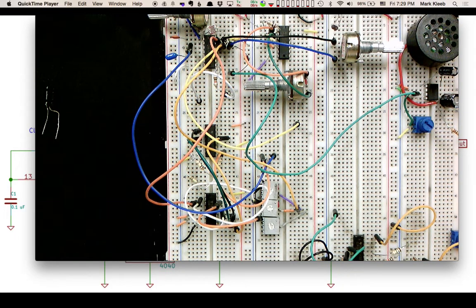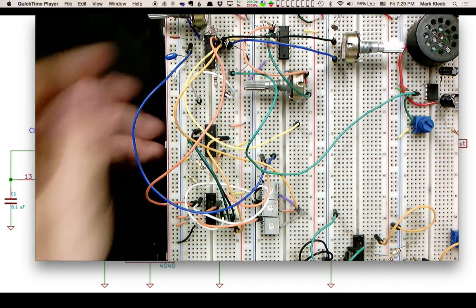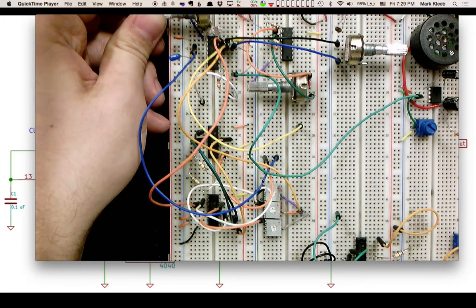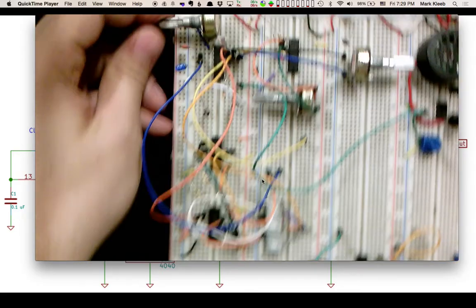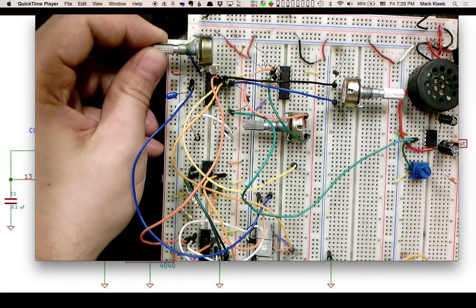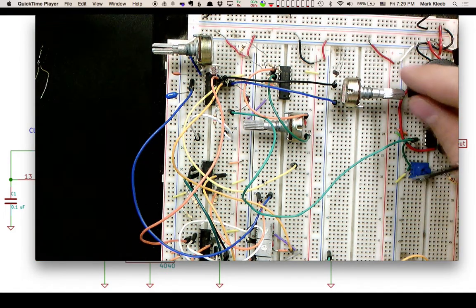And then everywhere that I hear that low frequency, it's because I don't have a trim pot hooked up to that pin. So it defaults back to my base frequency. And now my original oscillator becomes my clock, and my second oscillator is the pitch.